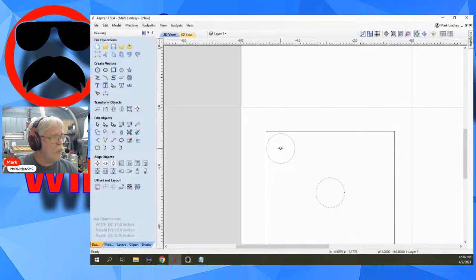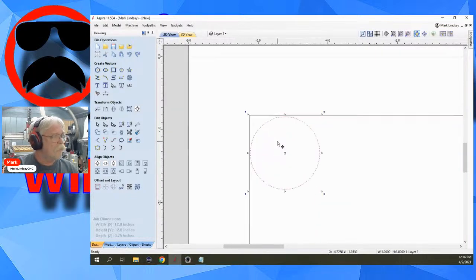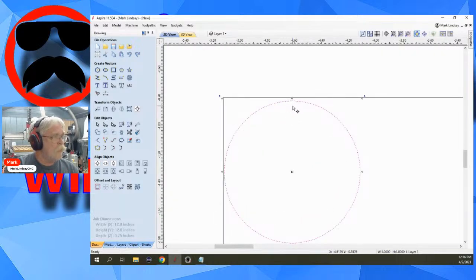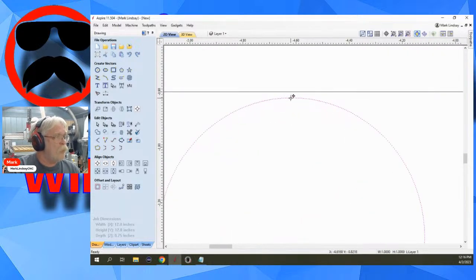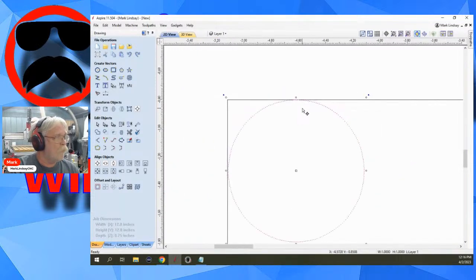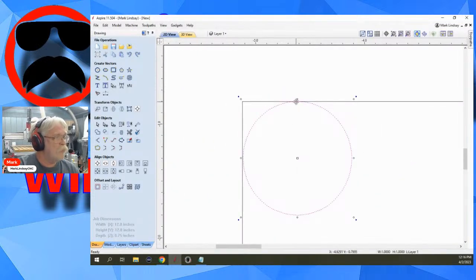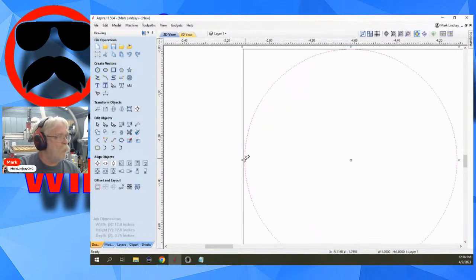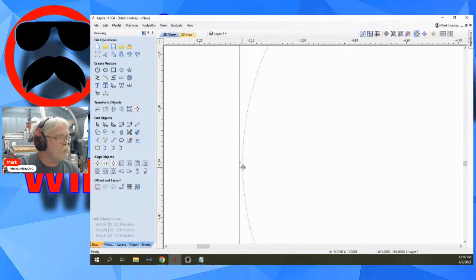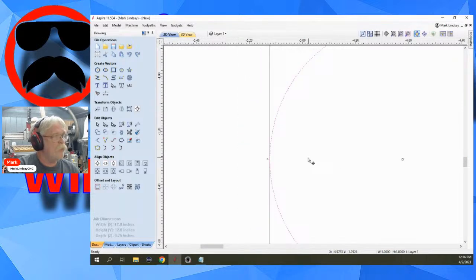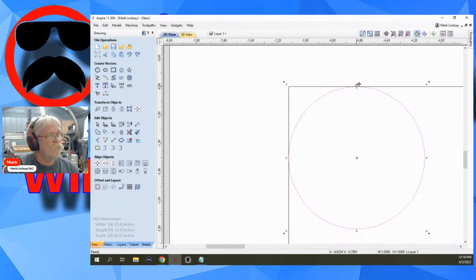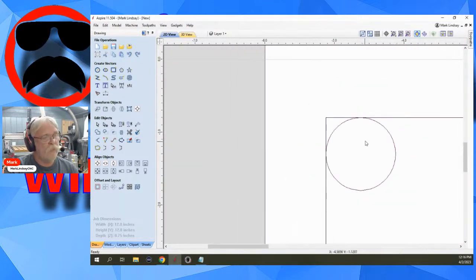When I bring it up in here to try to machine out this corner, what I'm not going to be able to reach into this corner here is the radius of this bit. So that's the simple answer. The radius of the bit is half of the diameter.